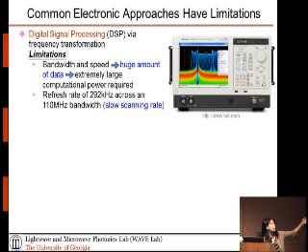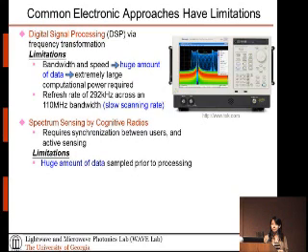On the right is a very high-end, state-of-the-art real-time spectrum analyzer. It's very decent, except that it's relatively slow. The refresh rate of the screen is only 292 kilohertz over just a 110 megahertz range. So it's relatively slow. And the second approach is spectrum scanning by cognitive radios.